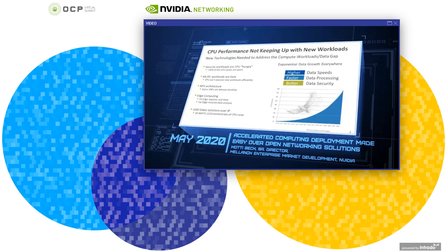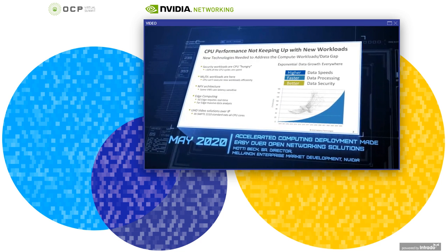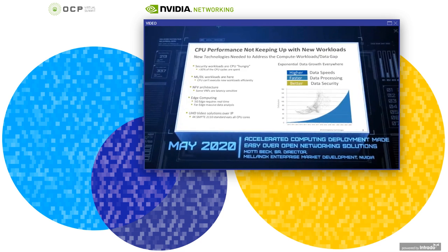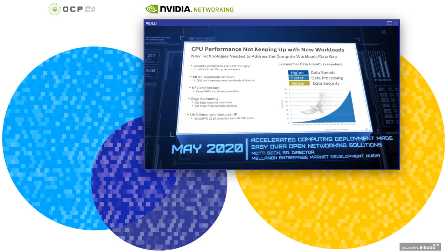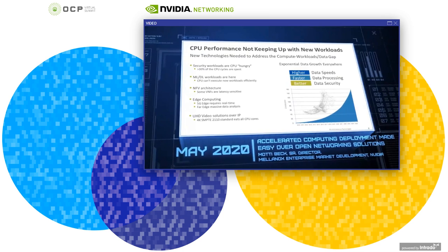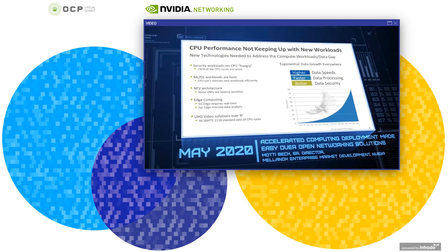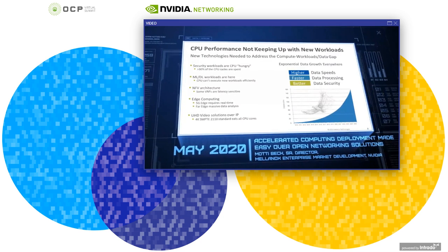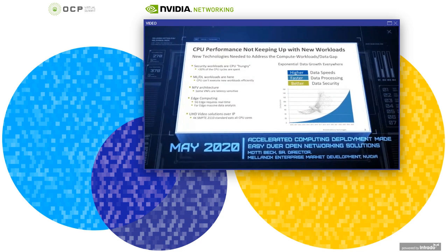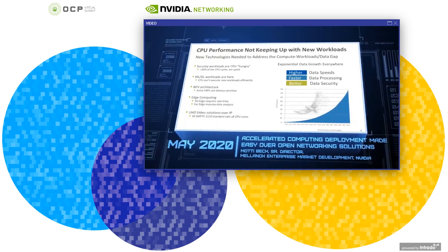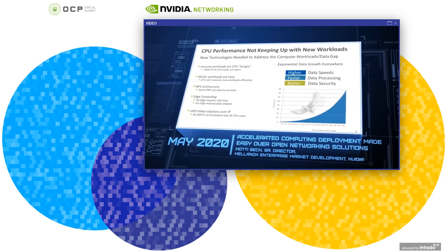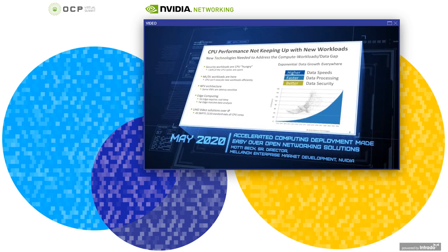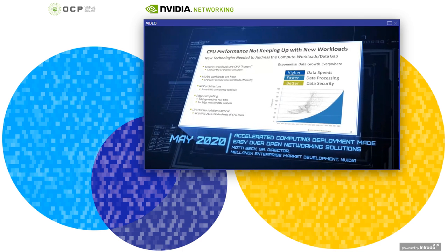It's a new standard called SMPTE 2110. This is a standard that enables video over IP solutions for high resolution, even more than 4K. And in those cases, you need to meet a very accurate, specific timing requirement. Doing it on the CPU itself, with a protocol called PTP, if you're familiar with it, you still can do it, but it's not going to be as good as doing it in the hardware itself, which modern or advanced NICs have as an offload.